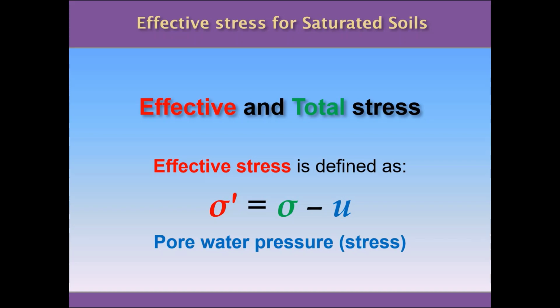And the total stress is a stress as well, and of course, the pore water pressure is as well a stress, but it's a particular type of stress because it's a spheric stress. We are going to discuss this in future videos. But the important thing to remember is that the definition is simple, but the importance is huge. So again, the effective stress is equal to the total stress minus the pore water pressure. So we are taking into account not only the loads produced by the weights of the soil and external forces, but the effect of the water pressure in the pores of the soil.